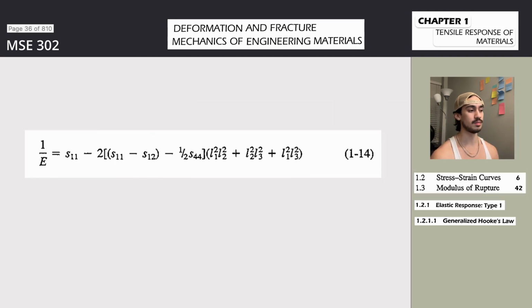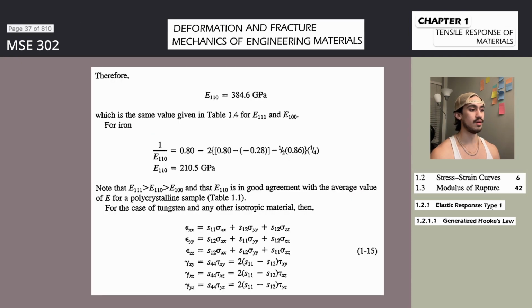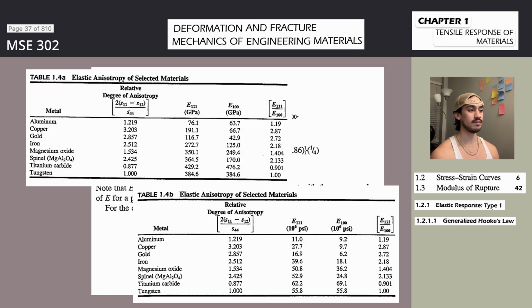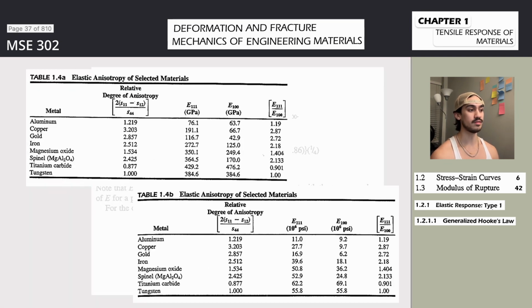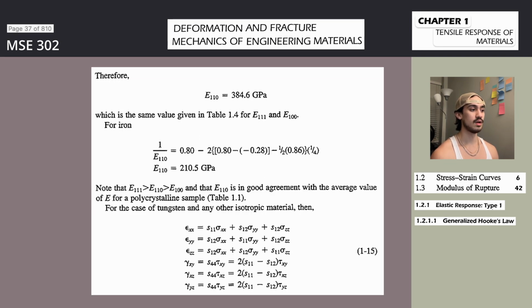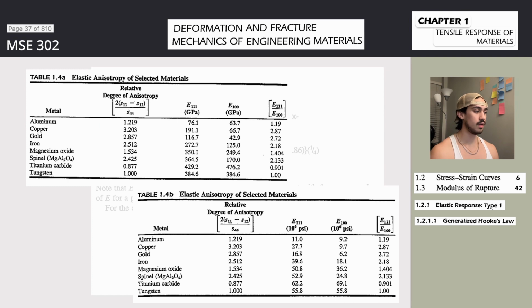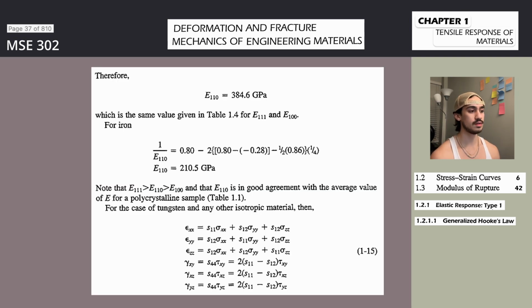The ultimate tensile strength is defined as the maximum load divided by the initial cross-sectional area, while the true fracture stress is the load at fracture divided by the final cross-sectional area, with correction made for any localized deformation, necking, in the final fracture region. A compilation of tensile properties for a number of engineering materials is given in Tables 1.6 and 1.7.